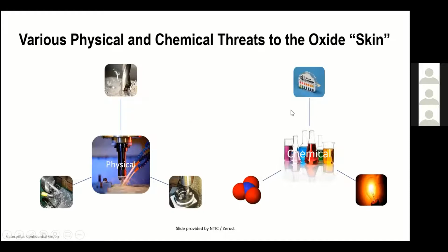And then chemically, because in the manufacturing environment, if you look at the physical picture in the middle on the left-hand side, we're using what we call a metalworking fluid or a coolant. That is used to take the heat away from the tooling as one aspect, and the same with the parts, so your tooling doesn't burn up.